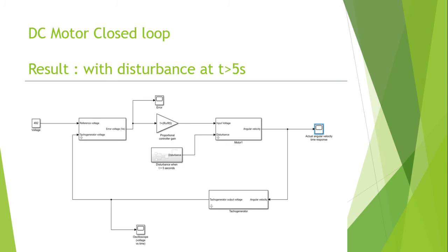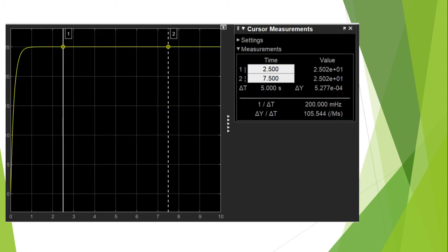Also, we put proper resistances: R1 and R2 we put about 1 kilo ohm, R3 and R4 we put about 500 ohm, and R5 about 10 kilo ohm. After we do the calculation of RV, we get RV is about 292 ohm.